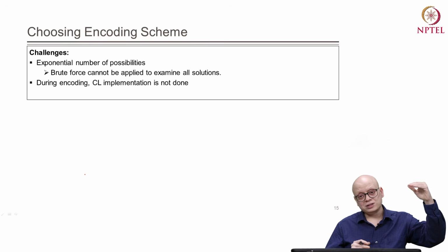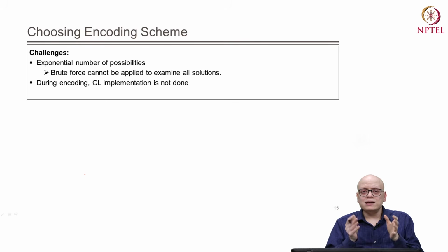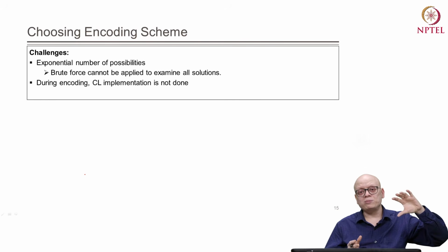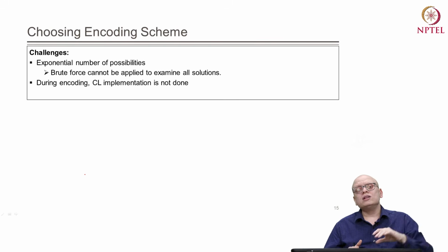The other challenge is that though we have discussed combinational logic optimization first and then sequential logic optimization, we have done this because it is easy to understand sequential logic optimization after understanding combinational logic optimization. But in practice, sequential logic optimization is typically done before combinational logic optimization.